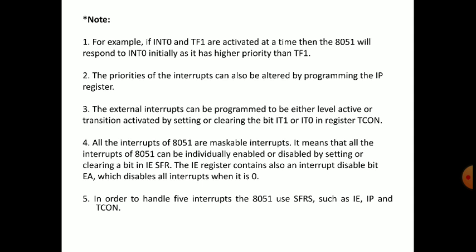All the interrupts of 8051 are maskable interrupts. They can be masked. It means that all the interrupts of 8051 can be individually enabled or disabled by setting or clearing a bit in the IE interrupt enable SFR. We have already discussed this register in the previous video lessons. IE register, interrupt enable register. These are maskable interrupts. The IE register contains also an interrupt disable bit EA, which disables all interrupts when it is 0.